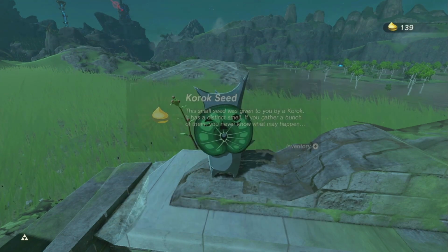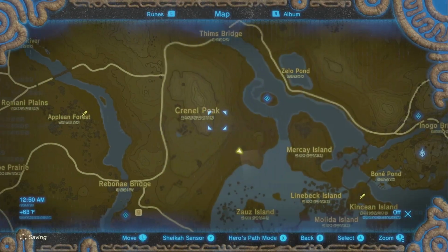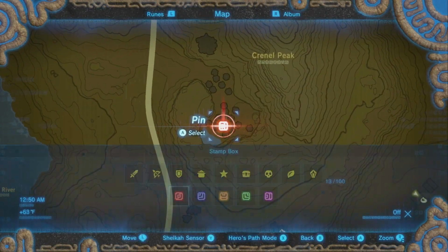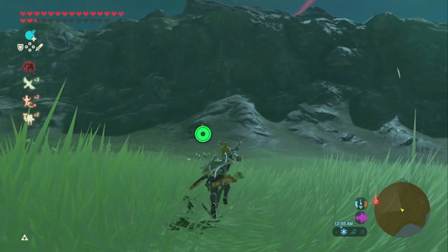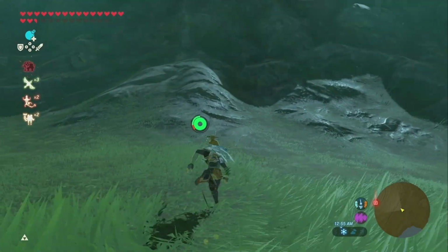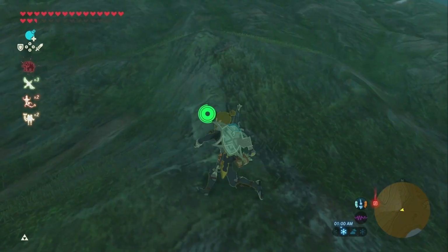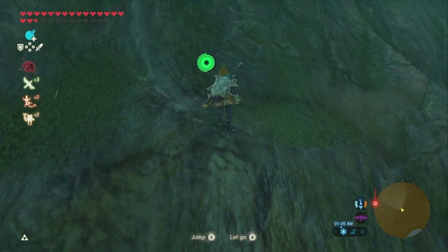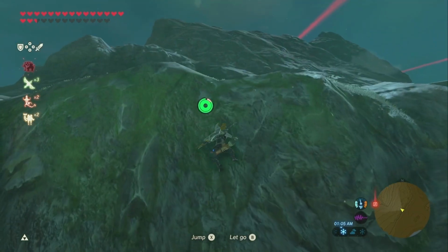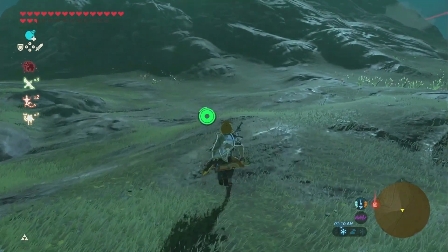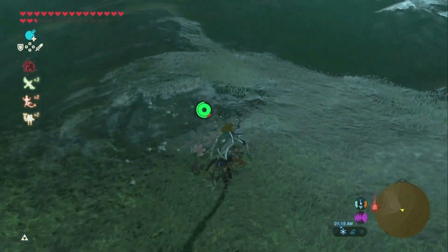Inadequate clearance from combustibles. Most water heaters do not have large requirements for combustible clearances. Clearances of less than 6 inches are common. Some gas units only need 1 inch clearance. There does, however, have to be adequate working space, [24 inches] commonly, around the heater to service the burner and replace the heater. Doors into closets or rooms with water heaters should be wide enough to allow for removal